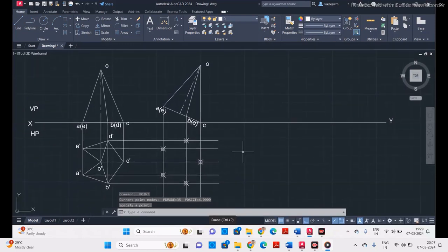So after putting the point, now you have to connect all the corners. Before that, at this point you will have two corners. C and O will fall on the same point. Corner C and this common point, the apex point, will fall on the same line. First connect the bottom face, which is a pentagon. Start from A. Before connecting the pentagon, you will give the names to all the corners.